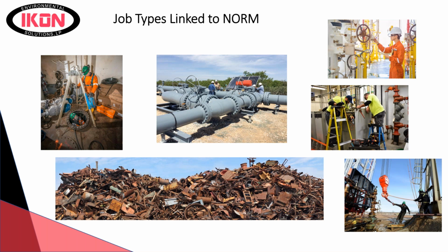The other thing is, if it's one that doesn't have a lot of buildup, we find they don't tend to get cleaned as often. People aren't running their pigging tools as much. People aren't pulling their pumps and their exchangers as often because they don't get fouled. The reason they pull them is because they see a drop in efficiency in their plant. They're not going out there cutting a coupon out looking for NORM. If it doesn't affect their productivity, it's not an issue. We've seen the cleanest stainless pipes that are still polished, and those can be the hottest things you see. It doesn't necessarily have to be, because your atoms, you can't see them, so the activity in there is still just as high.